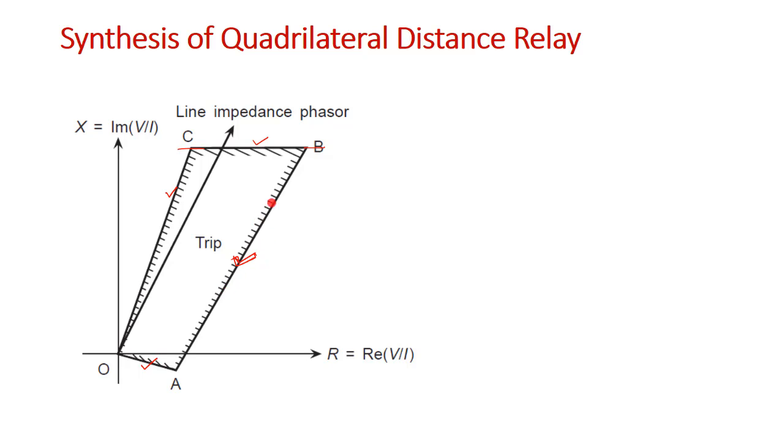It is exactly equal to the reactance relay, but with some angle. In the case of the reactance relay we consider the reactance, but here we consider the impedance, therefore it makes an angle. So this will be the trip region for this reactance relay, and this will be your restraining region. Therefore we call it the angle impedance relay.